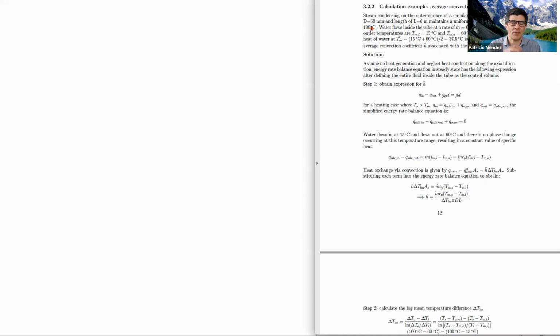If you remember, we said that in heat exchangers, we want the thermal resistance of the pipe to be so small that there is essentially no temperature difference between inside and outside the walls of a tube. So it doesn't really matter, but this is the inner surface temperature that is very close to the outer surface temperature of the pipe, because the thermal resistance of the pipe itself should be so small.